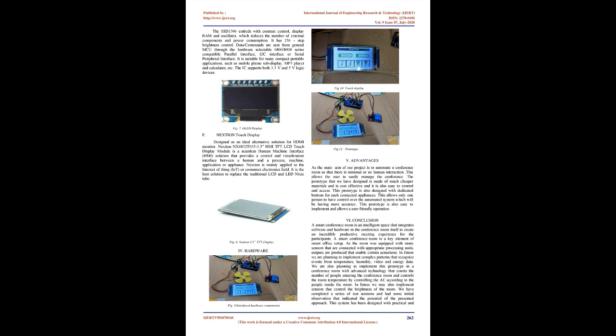Common, this is the pin we should connect to the signal with which we are planning to switch. NC, normally closed. A normally closed configuration is used when you want to turn off the relay by default. In this configuration the relay is always closed and remains closed until you send a signal from the Arduino to the relay module to open the circuit.